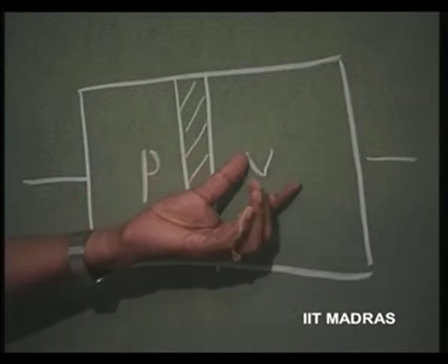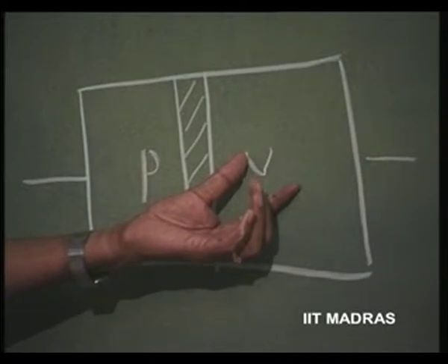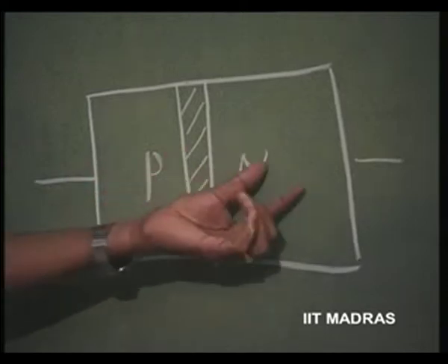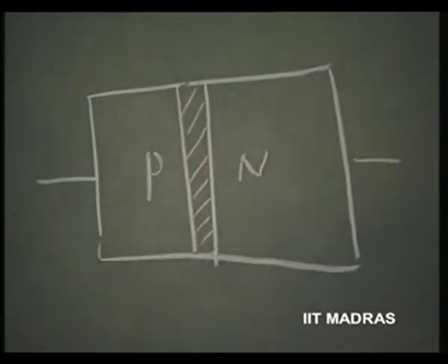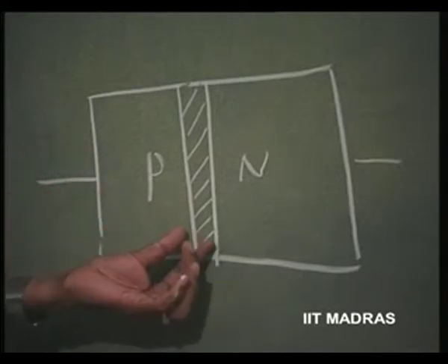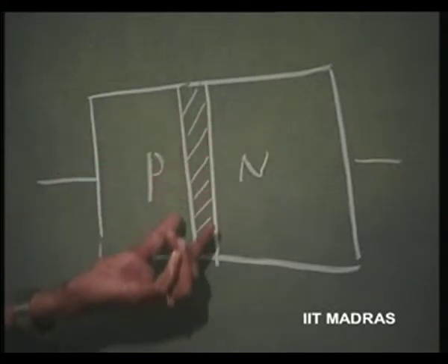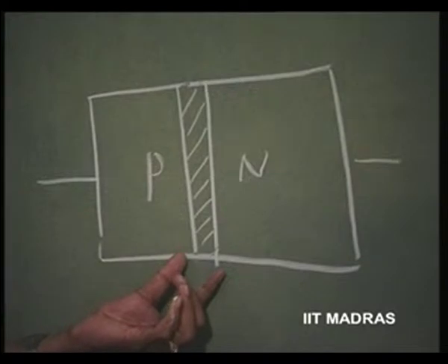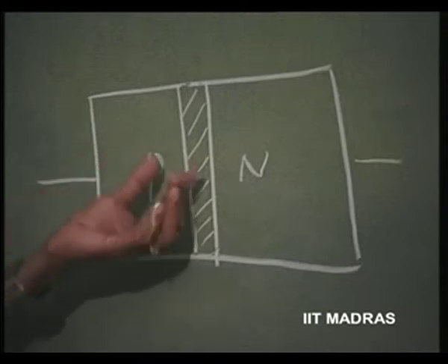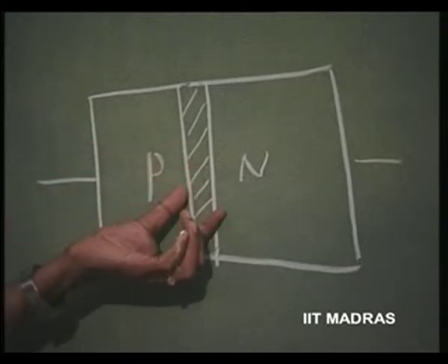Here we have majority carriers which are electrons, but minority carriers which are holes. Even though for the holes here as well as the electrons here there is a barrier potential hill corresponding to 0.5 to 0.7 V, because of the existence of the depletion layer. This happens the moment I form the junction. For us to have an equilibrium here, a potential hill is created.